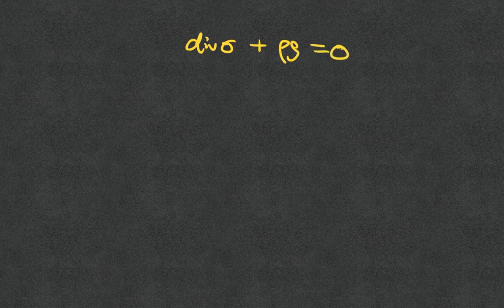And then for the undrained case, I just want to put the undrained case first, because the difference between the undrained case and the drained case is simply the Darcy's law term. Okay, you see what I mean? So if I write one, you probably can get the other two, but the undrained case is always the worst scenario, where if you don't have the inf-sup condition, it will trigger instability. Okay, so the first thing you may want to check is whether this thing works.